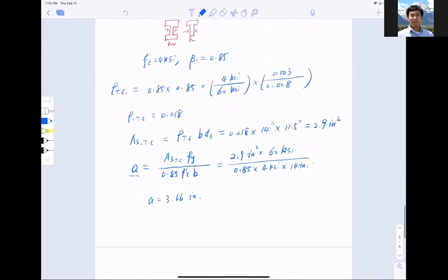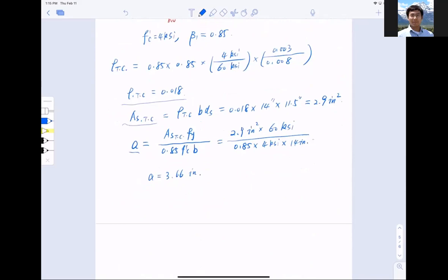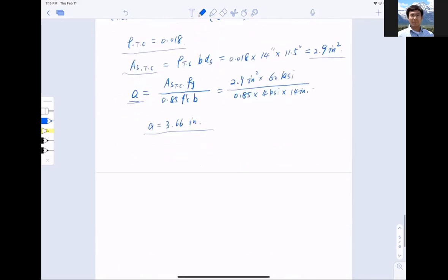We use that equation and arrive at a ratio for reinforcement area, calculate that reinforcement area, bring it back to calculate the effective compressive zone. And carrying on with this effective compressive zone, I now obtain my moment capacity, and I want to notify you that this is basically MN1, okay? I'll explain why. I can calculate using AS times Fy, which is essentially just the tension force, and ds minus half A, that is the lever arm or distance.